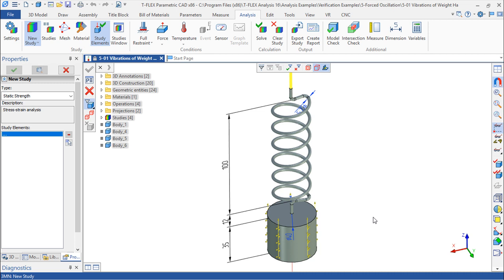Finally, in terms of this introductory information, the results of the analysis of this forced oscillation module include the following quantities: the displacement amplitudes in nodes of the finite element mesh, and finally the oscillation overloads, defined as a ratio of the oscillation acceleration to the gravitational acceleration.